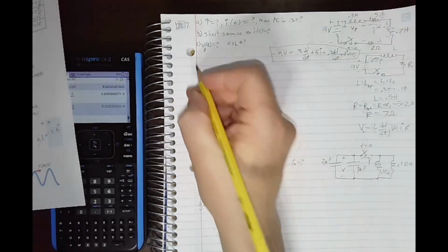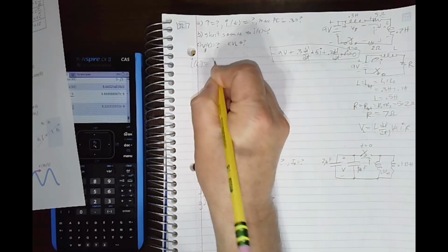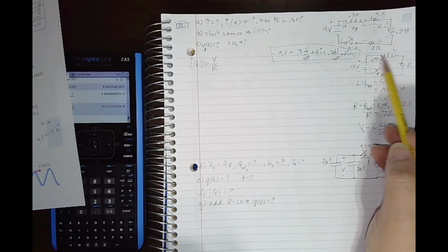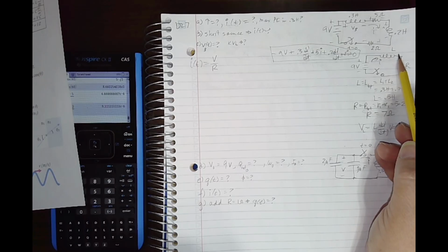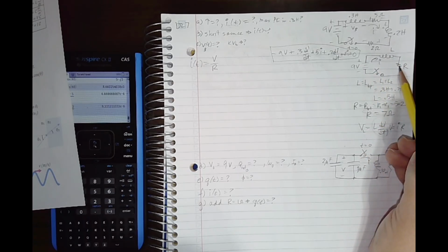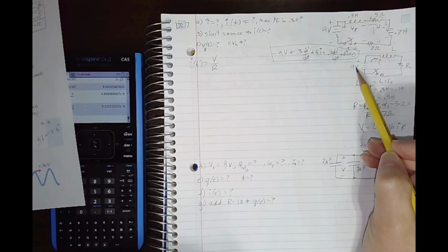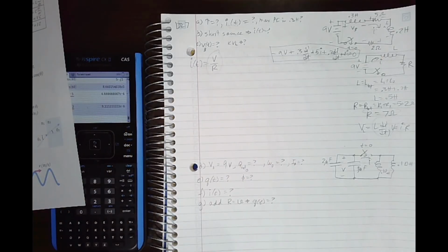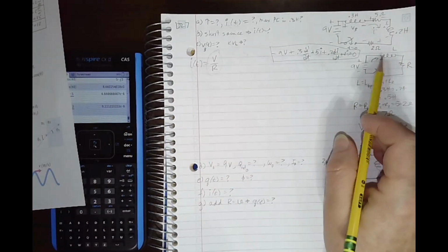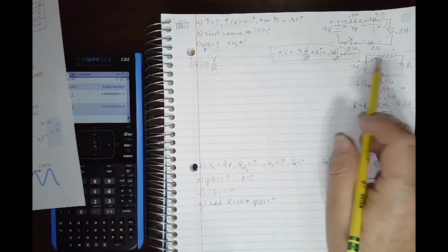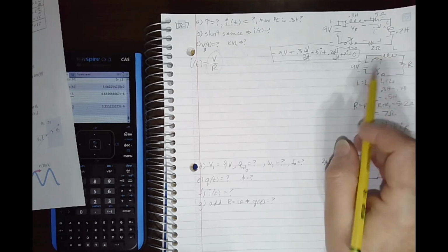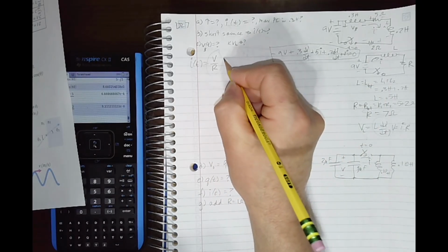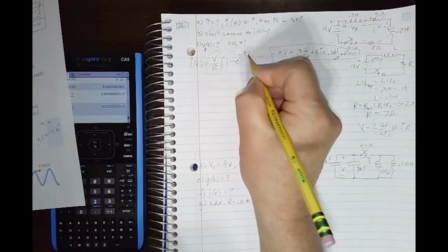All right, so I of t is going to be V over R. How does it get to be V over R? If L is 0, or if there's 0 resistance, the voltage across this is 0, then the only thing in the circuit is a resistor, so the current is just the source voltage divided by resistance. So that's where this maximum current comes from. The maximum it can be is when the inductor is acting like a 0 resistance, like a short circuit, just like there's a wire there, and the only thing in there is the R. All right, so that's the maximum, and then we have 1 minus e to the negative t over tau.